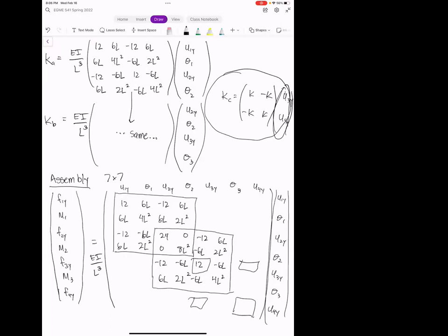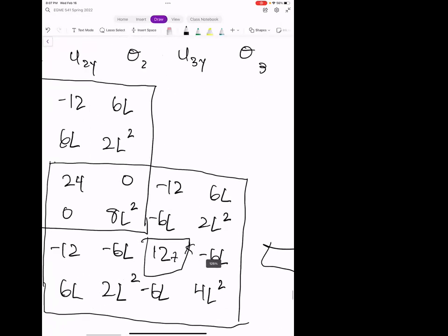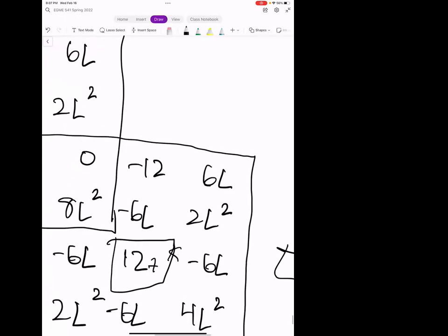And then since we have this multiplier out in the front for EI over L cubed, we need to account for that. That assumes that we multiply this through the entire thing. So if we have our spring constant here, we have to multiply it by the reciprocal of this. So this is going to be plus K. Let me zoom in on this. Actually, let me go ahead and remove this box.